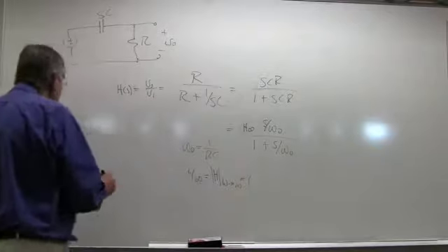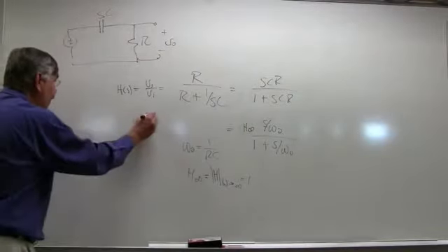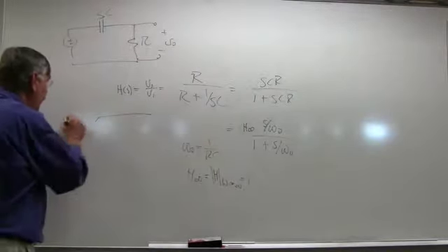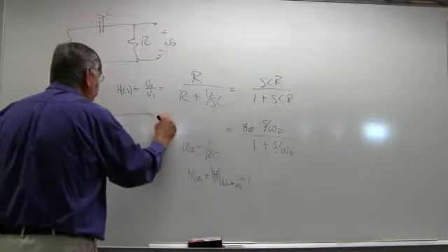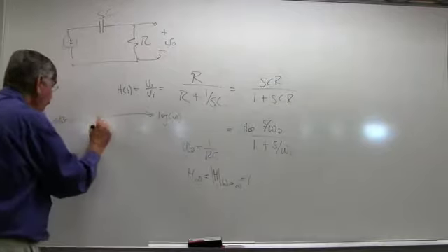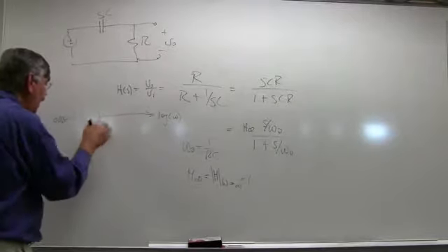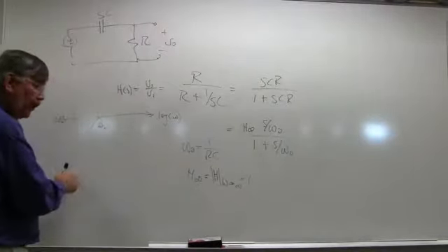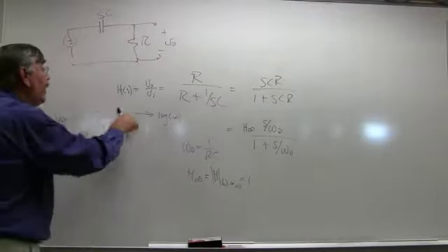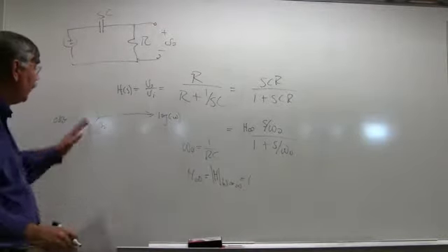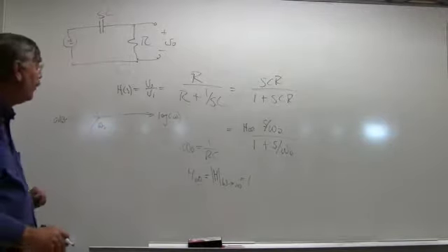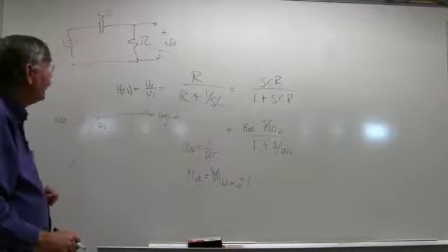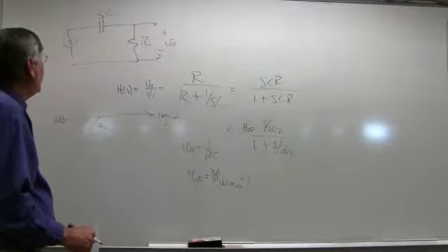And so this is just like the Bode plot that we had before, except it does this. So this is 0 dB, this is log frequency going this way, this is omega 0, and this is of course plus 20 dB per decade, I'm not going to write it down. So this passes high frequencies and attenuates low frequencies, so this is called a high pass filter, okay? Filtering out the low frequencies.